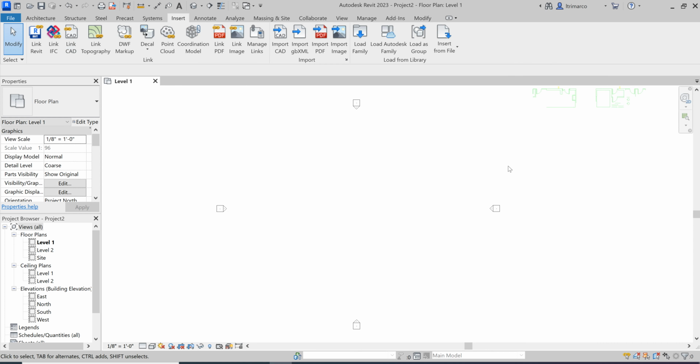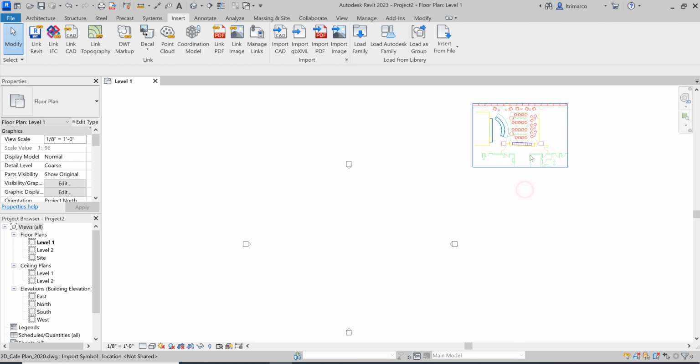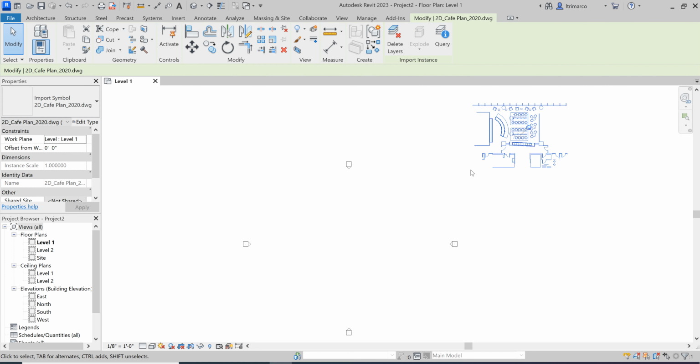And you might notice in the upper right hand corner that if I zoom out, I can see my AutoCAD file loaded. As I select it, you can see that it instantly hovers over a boundary box, if you will. If I select it, all of the parts and pieces that were drawn in AutoCAD, all the objects, get selected and turn blue, and you'll see a little pin. The pin is obviously representing that it is locked.